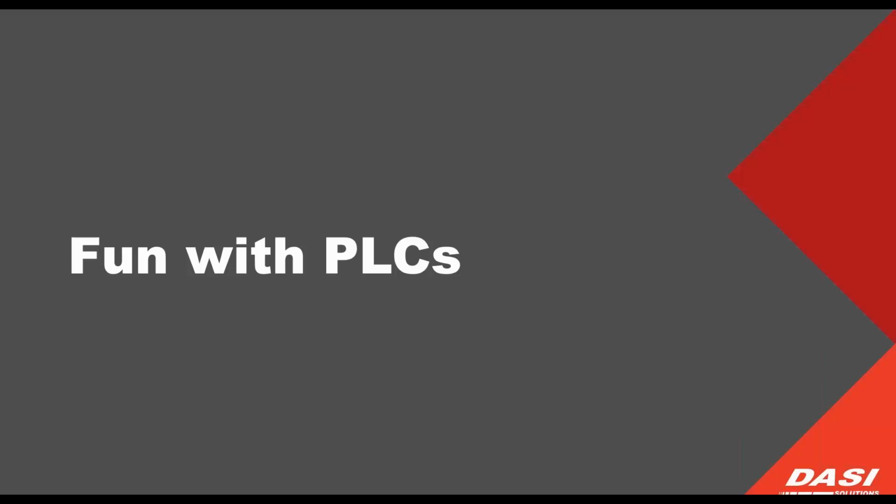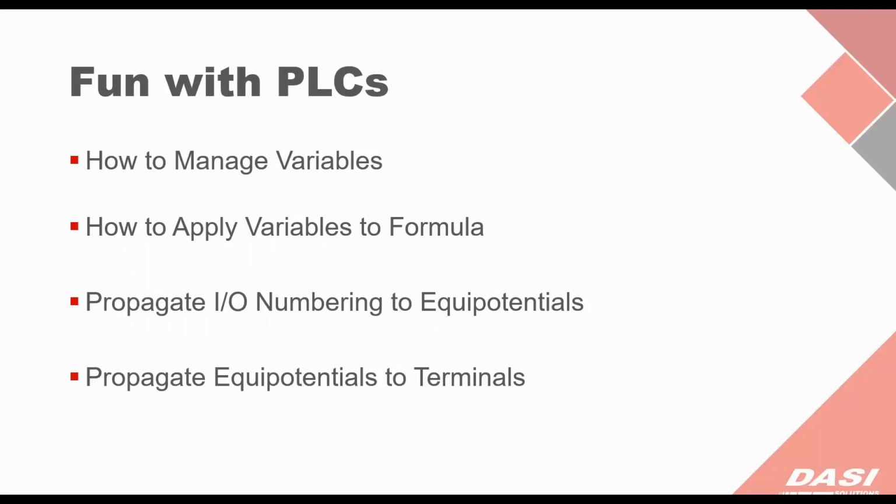Lastly here, I'm going to go ahead and get into the fun with the PLCs. Now, this area, I am covering just how you manage those variables and then being able to apply them into the formulas, where they actually come from, because I know a lot of people have had lots of questions about this. So I also want to show you how you can then propagate those I/O numbering to the equipotential wire numbers, as well as then push them from the wires to your terminals.